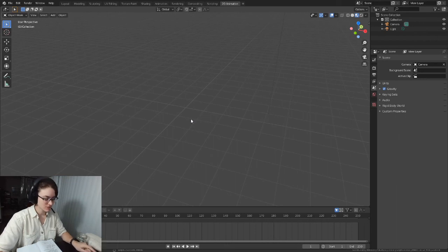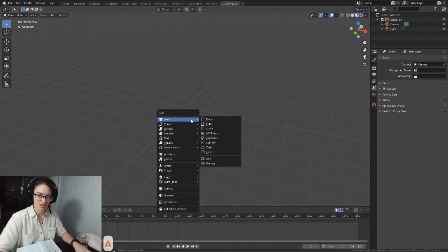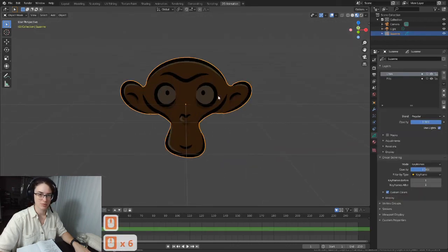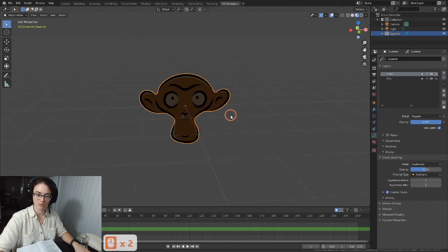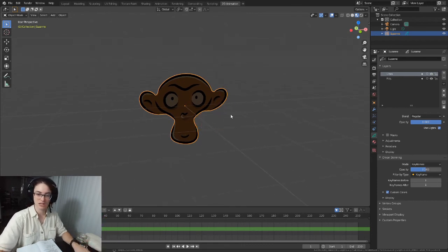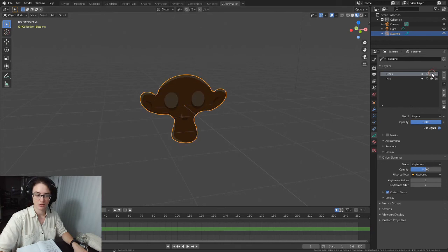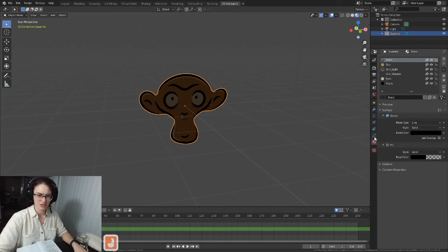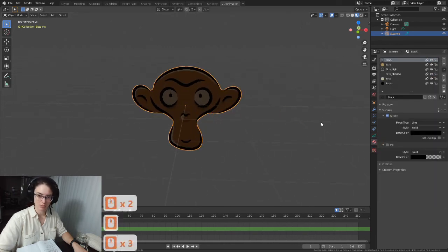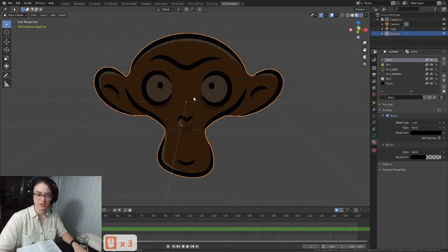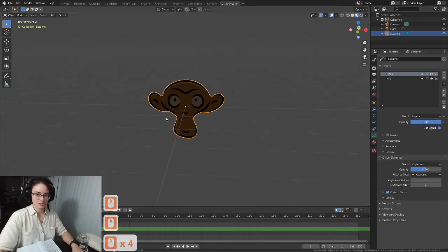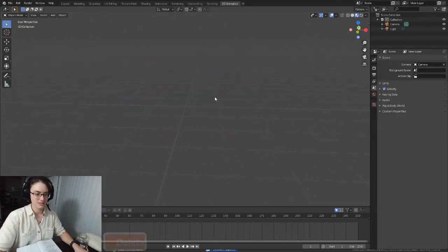So let's first bring in our Grease Pencil object. So Shift A, there is a Grease Pencil section. It has a few things. We're just going to go with blank, but you can also pull up one of the pre-existing ones just to play around with it, or any of the tools I introduced today if that helps you out. You can also see how they separate and do the materials for their drawing, which might help with you in the future. So they actually drew in shadows on this guy. So I'm gonna delete him, we don't want him. Or it's a lady monkey.